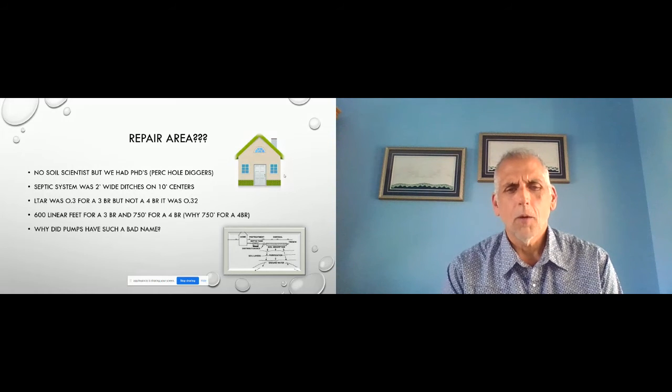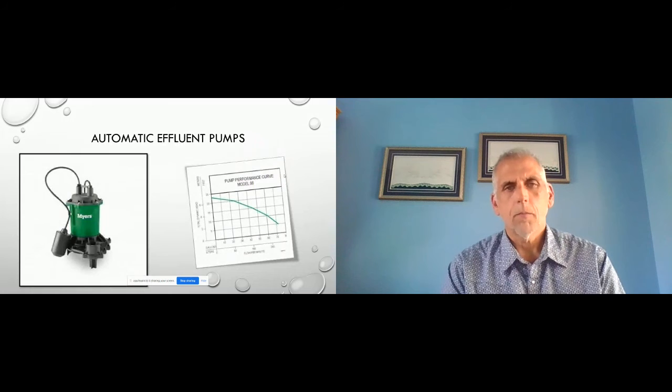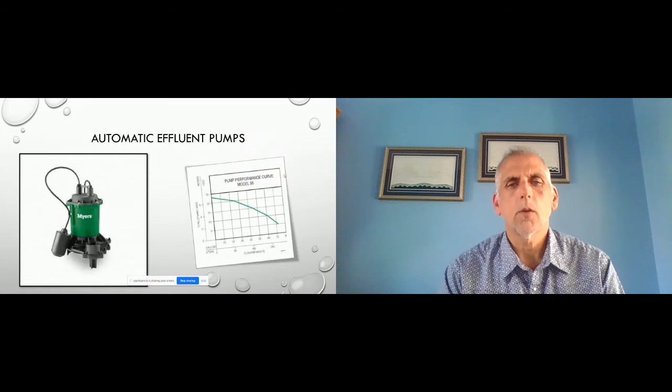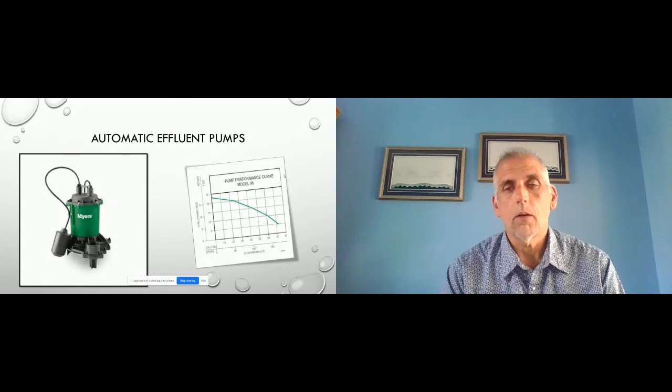But why did pumps have such a bad name? Well, they had a bad name because there were a lot of people that would not install the correct pump. They would install these little automatic pumps, and they would cut on and start running at about 15 to 20 gallons. And so they were on and off all day long, and they burn out. And so people were having to replace them.